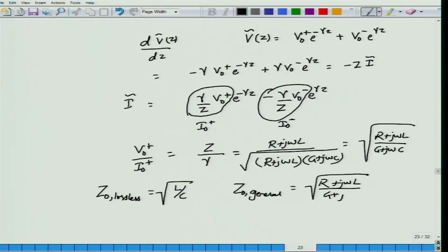This means that not only will the voltage at one particular z be different from the voltage at another point in terms of phase, but the amplitude also will be different. Usually the amplitude decays, therefore the voltage, as you start propagating along the transmission line towards the load, will not only reduce in amplitude but will also change in phase. These also introduce a couple of additional factors that we will consider in the next few modules.